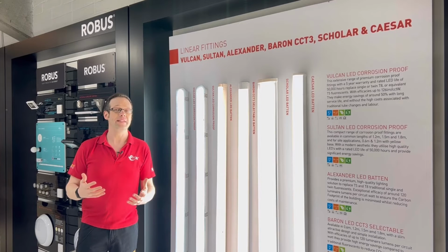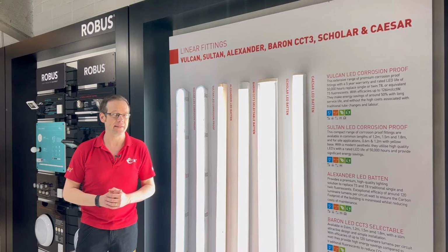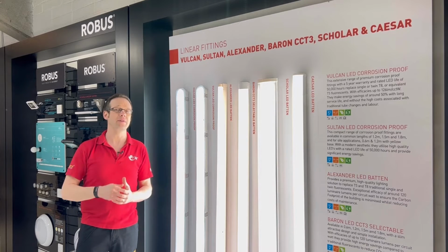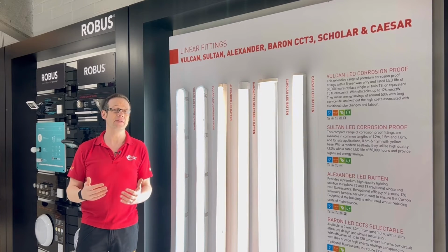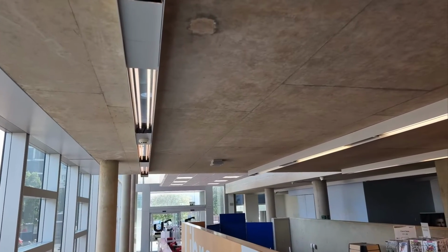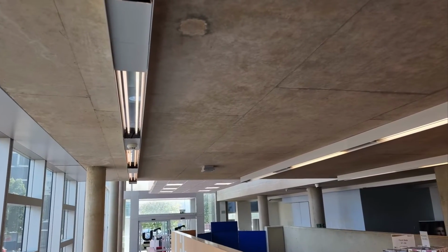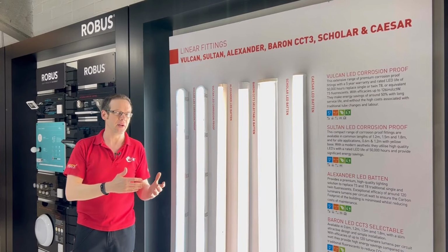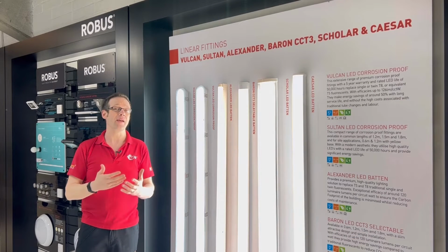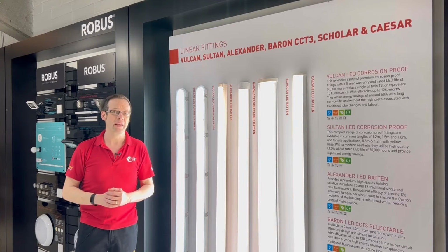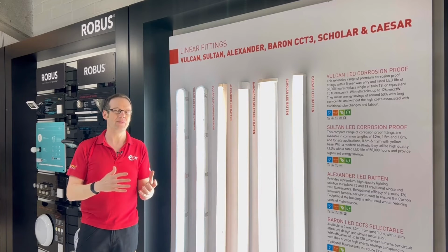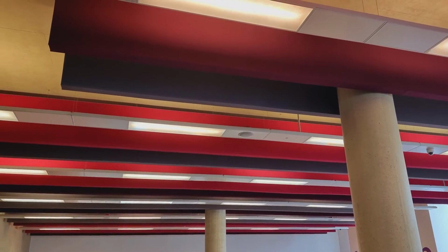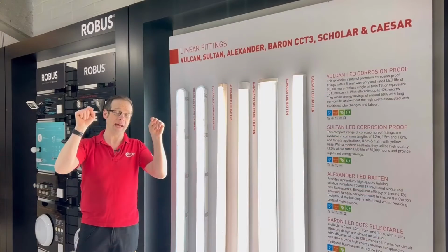Now, all of these fittings are perfect for where suspended ceilings are being used. However, there's been quite a shift in recent years for new buildings in these areas not to have suspended ceilings, but just to leave the concrete soffit of the floor above exposed. This is partly an exercise in reducing the build cost, but also because it can create a more pleasant environment to work in. The echoing, unpleasant sounds that would naturally ensue are minimised by installing big pads of acoustic material and then suspended light fittings that send light both up and down.